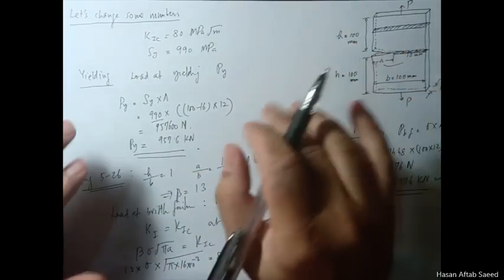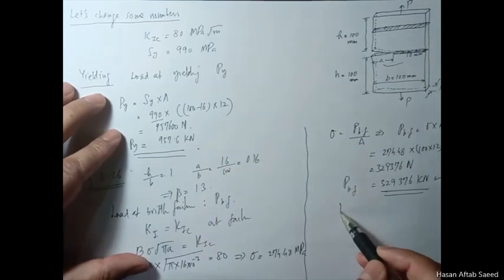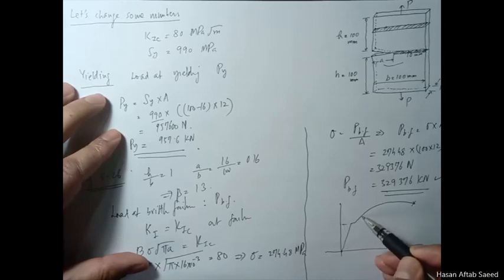Although this is slightly different, if I talk about the uniaxial tension test, we are familiar with this sort of a curve, because there's no sudden failure there. The component yields, and then it strain hardens, and then there's necking. Actually, the stress goes even higher, and then it breaks at a certain time. But there's a lot of warning, there's a lot of energy that goes in.